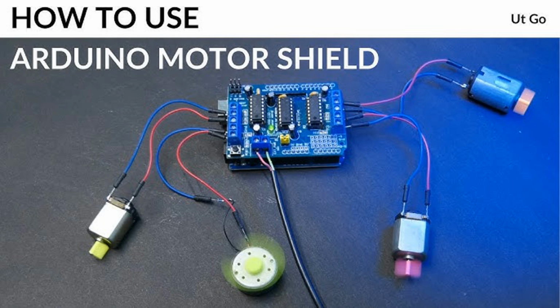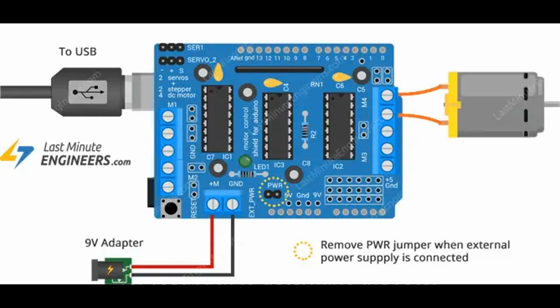2. BLDC motor drivers with Hall sensor feedback. Function. These drivers include Hall sensors, or encoders, for feedback to determine the rotor position. The Hall sensors provide real-time data about the motor's position, which allows the driver to commutate the motor correctly and ensure smooth operation. Operation. The driver uses feedback from the Hall sensors to determine the position of the rotor and select the appropriate phase of the motor to energize. This results in more accurate and efficient commutation, especially at low speeds or under load.